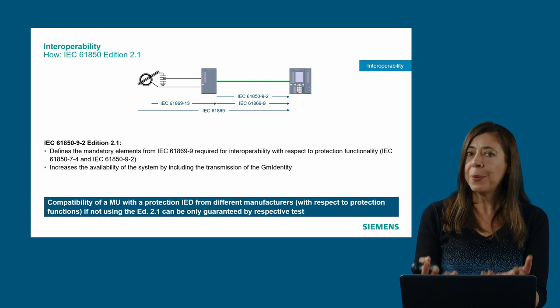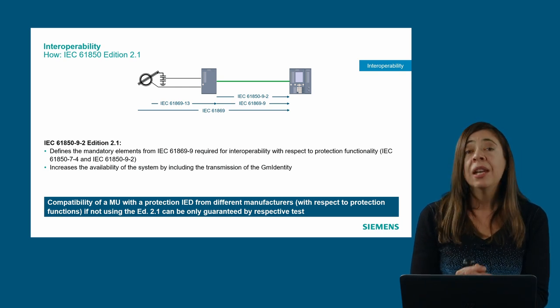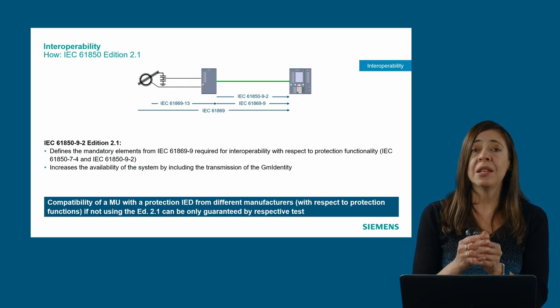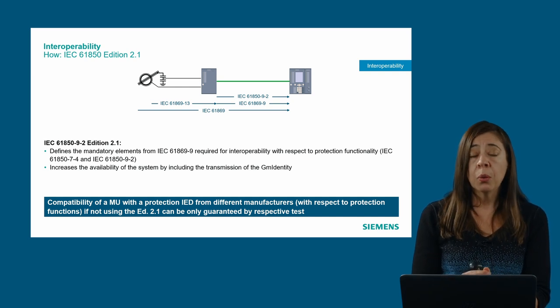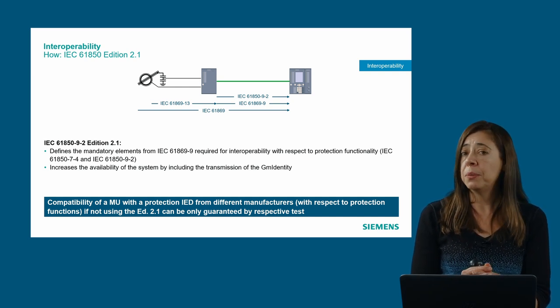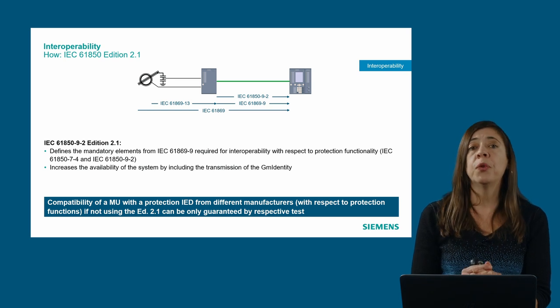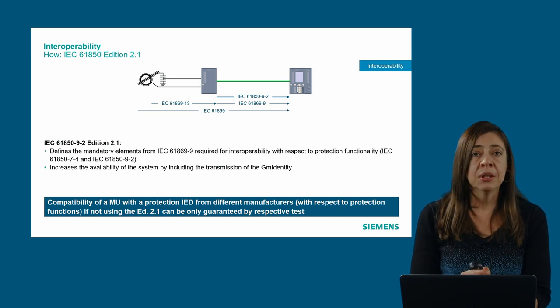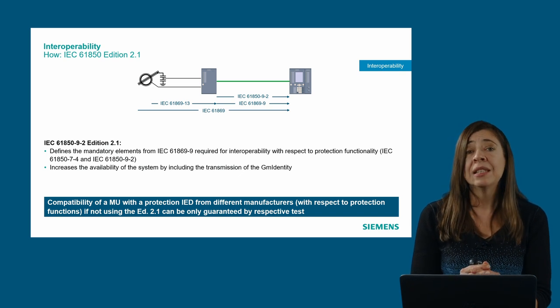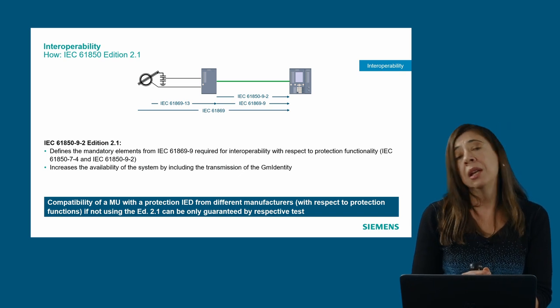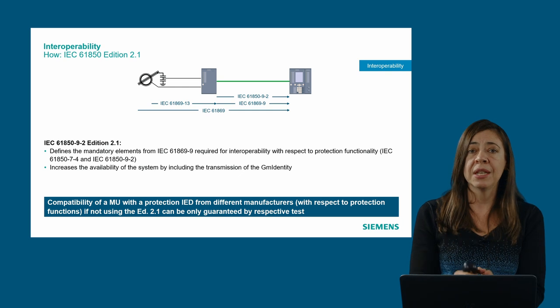So to take away with this interoperability topic, if you want to really grant the interoperability, then use the edition 2.1 when integrating devices from different vendors. If for any reason you cannot do it, then make sure to run special tests so that this interoperability is granted for your specific system.